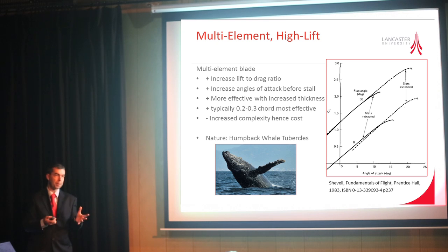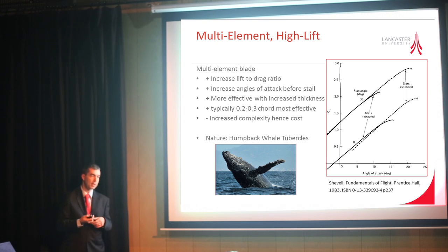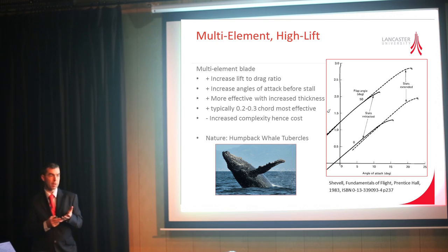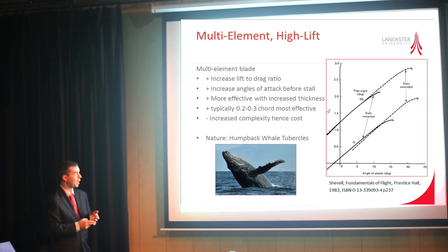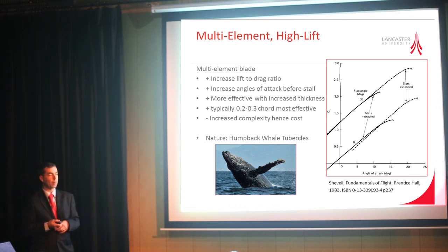So we know we can improve the lift. What we don't really know is, can we improve that lift without significantly increasing the drag that's acting on that turbine? Because in terms of turbine design, the critical point is having an appropriate ratio between the lift curve and the drag curve, or the lift to drag ratio. Optimize that, and typically you'll be optimizing the turbine.